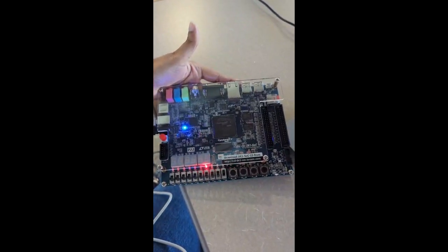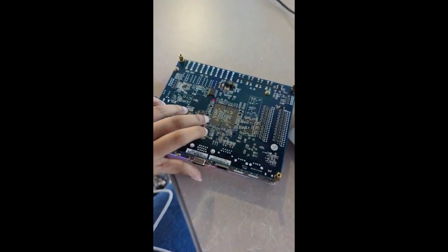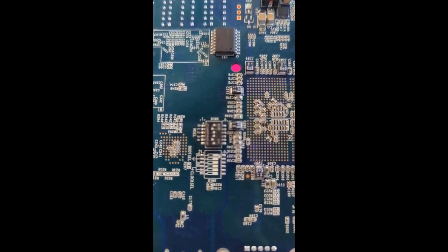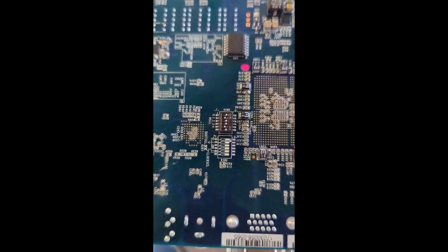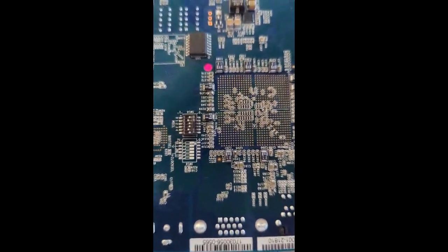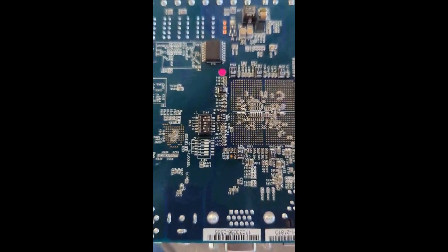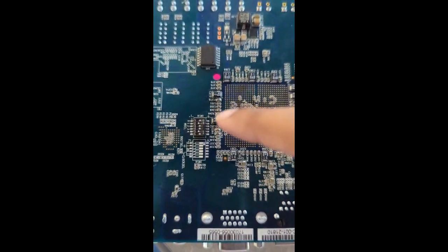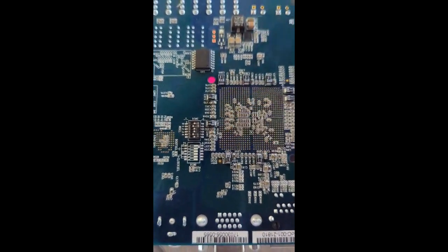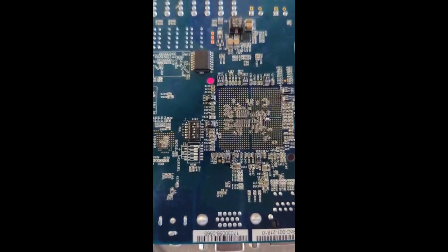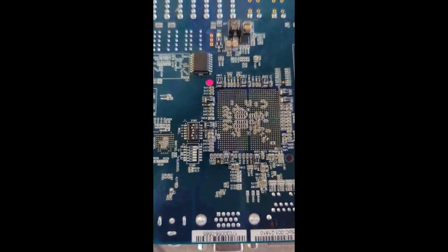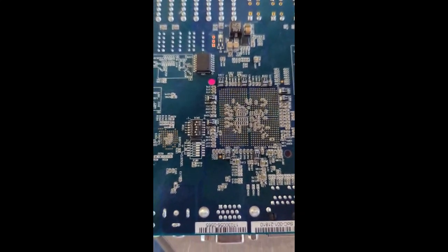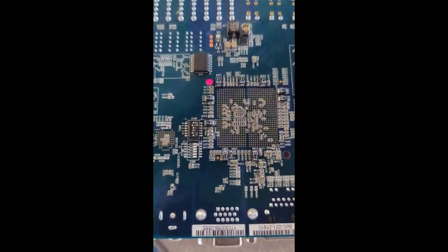Before flashing into the device, we first flip it over and then we go to the M select here. So we'll have to keep M select in this order where 0 to 4 is considered here as seen here. It's 0 and 1 here. This 0 is 0, 1 is 1, 2 is 0, 3 is 0, and 4 is 1. So we set it like this before flashing it completely into this device.